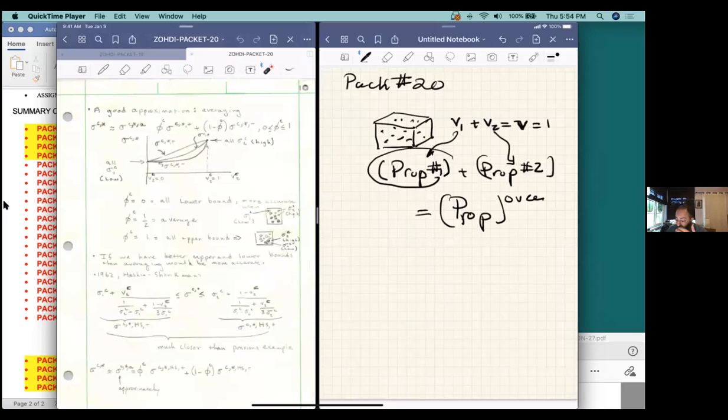Because of course, if you add particles to the system, like I'm showing you here, and I take clay and add metallic particles to it, even magnetized particles if I like, and then I apply some kind of magnetic field, this overall blob of clay with embedded microscale particles behaves like a magnetic piece of clay. That's a really fascinating thing to understand, because by making these mixtures you can use clay, which is really easy to form, and magnets, which are really not easy to form, materials like neodymium that are very fragile and fracture-untough. They break rather easily. So usually we granulate the hard-to-fabricate material and embed it in something nice and soft that we can bake. And then effectively we can produce these kinds of materials.